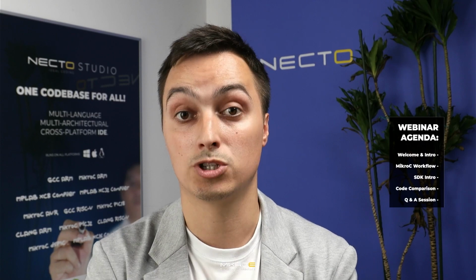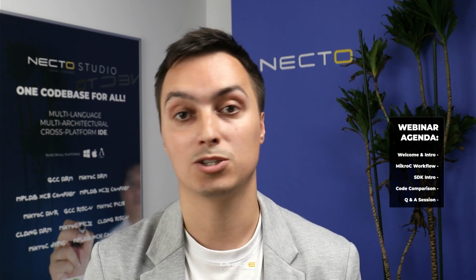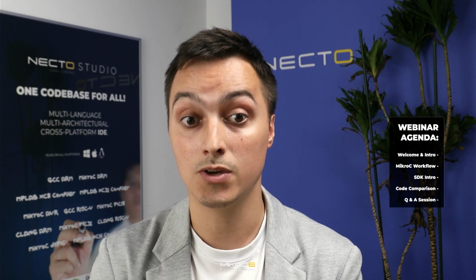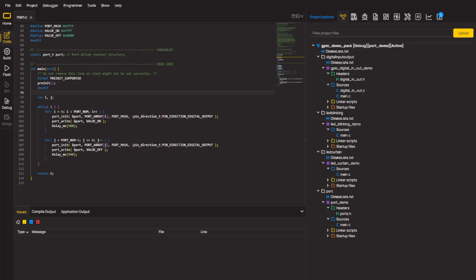Right, this was the practical MCU port demo, which toggled the pin voltage via bare metal code, and after that I showcased the SDK code doing exactly the same logic on two different microcontroller architectures. Now, inside that same GPIO demo pack, you also get the LED blinking demo, this one over here, and you get the GPIO digital in-out demo, this target over here, which basically shows how to configure pins as input and output.